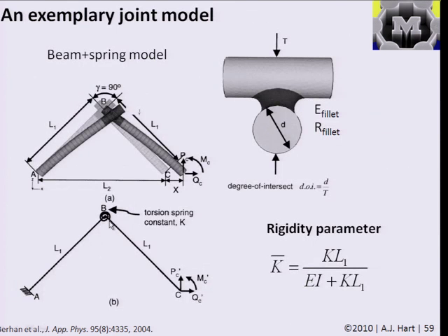So, for example, if we looked at one joint, there's been work, as shown in one of the readings, where you consider the nanotubes as individual beams, and you consider the connections between them as springs with particular characteristics. And if we thought of having a polymer at the interface between the two structures, we would have an assembly, and we could use, for example, quite traditional mechanics to consider the effective stiffness of this assembly. And you're certainly welcome to read this in more detail if you want.